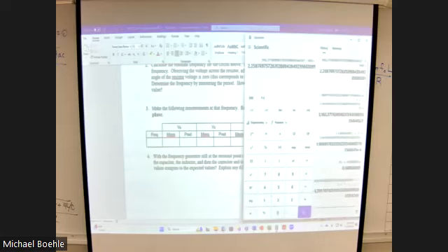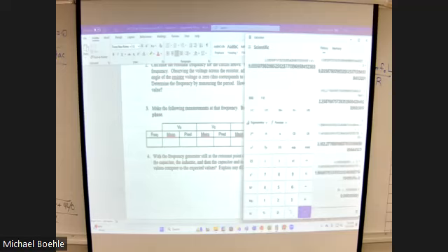Or a Q of about 2.26, roughly. Which means when I put in 4 volts peak to peak, I'm going to see at least 9 volts out.